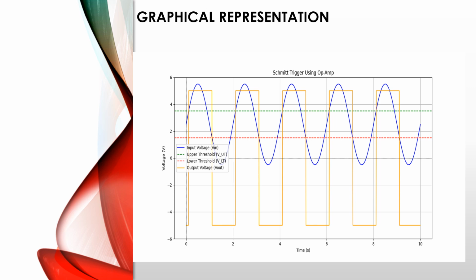Because in the non-inverting comparator circuit, we apply an input voltage at the non-inverting terminal and a reference voltage is applied to the inverting terminal, and we compare these two voltage levels. In case of the inverting comparator circuit, this work is repeated except the terminals have been changed, right?